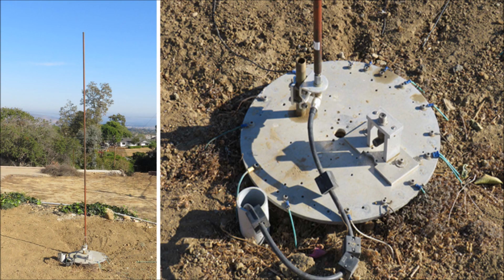Here is a practical and effective ground plane installation. It is a ground-mounted ground plane with over 20 random length radials. The radials do not need to be buried. A 10-meter quarter wave long copper pipe is the radiating element. A trimmed stainless steel CB whip will work just as well. Once the radiating element length is trimmed for the best SWR, the radiator is a true quarter wave resonant element, so no matching network, balun, or tuner is required.